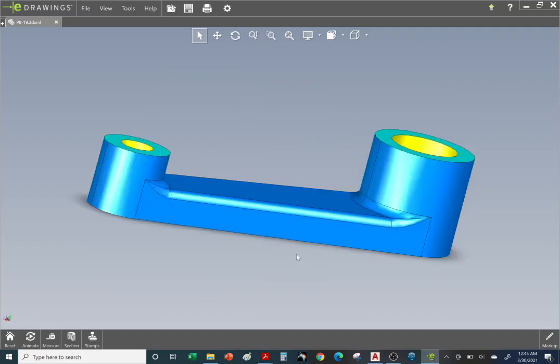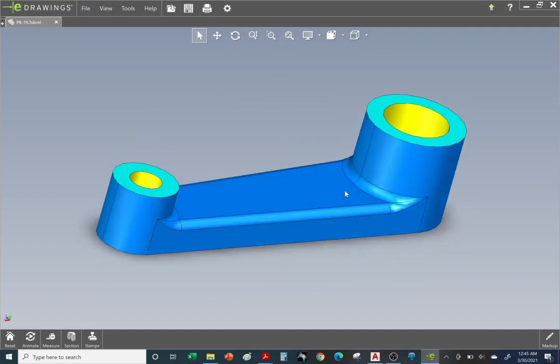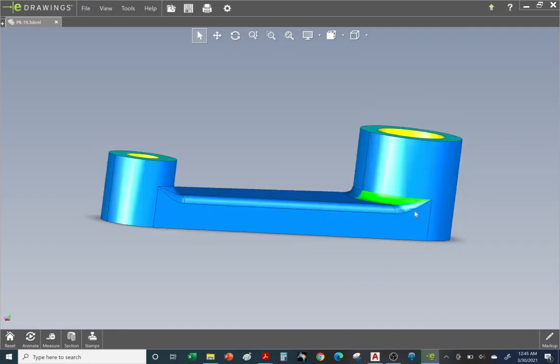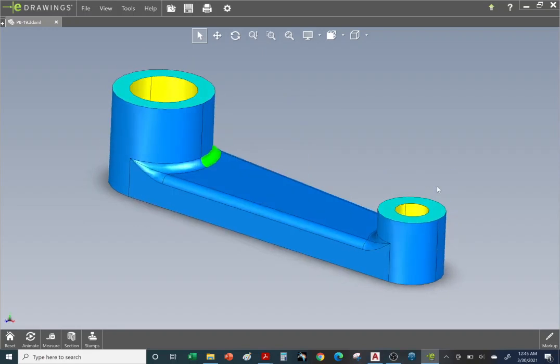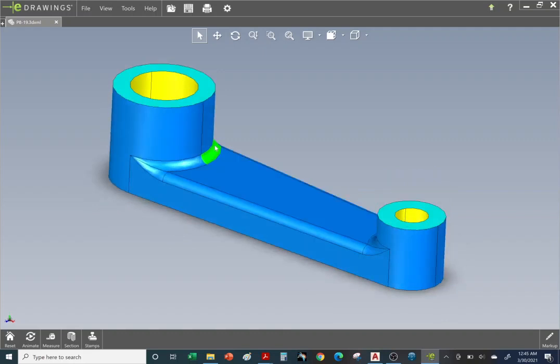All right, so here are the round edges or fillets, right? As you can see, they're 0.12 inches for our radius on this one. Okay, so one thing about this part is a part like this is actually poured into a mold. So this would be liquid metal, and let's say it's aluminum, and it's poured into a mold. And once it goes from a liquid to a solid, all this has a rough surface. So everything will have a rough surface, rough texture to it.